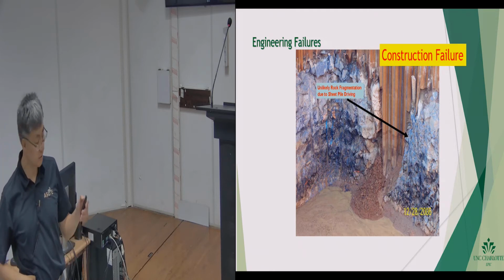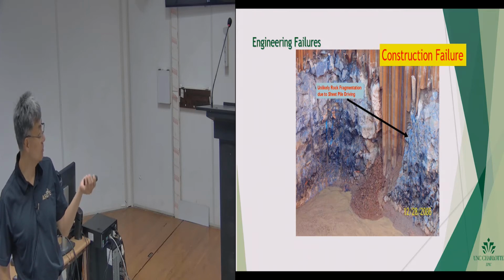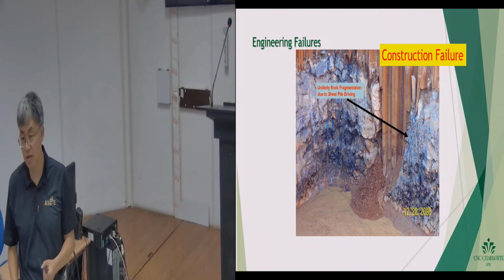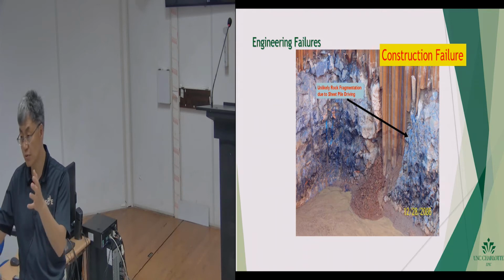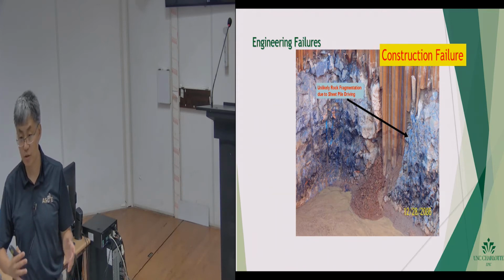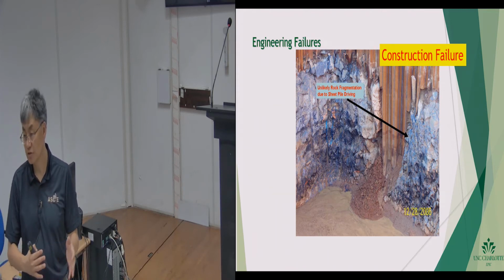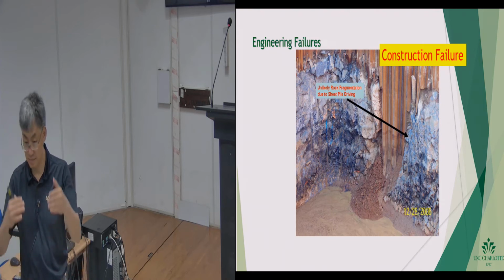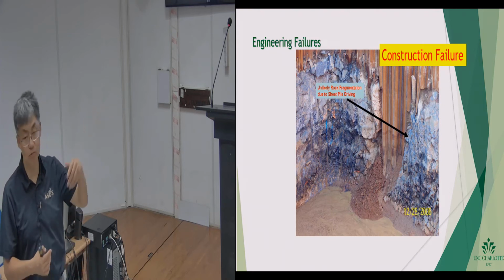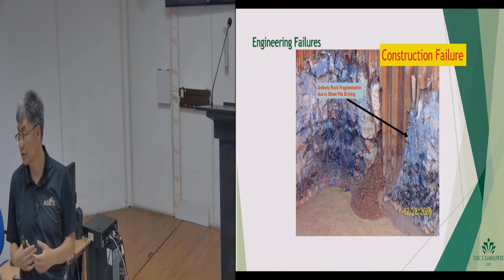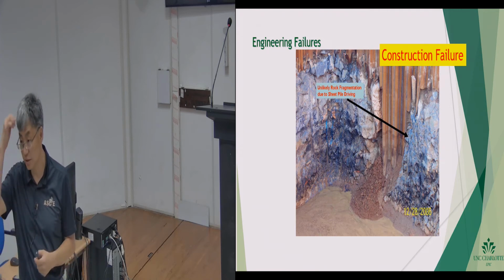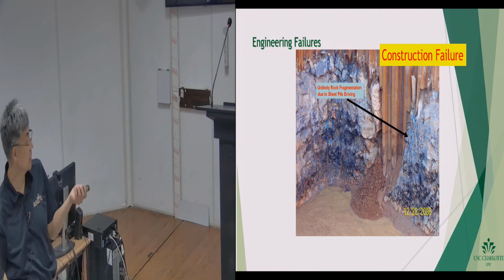The groundwater in this case happens naturally because this project is right next to a river. So we know that they have very, very soft soil, but the piles are supposed to be able to protect the area from any groundwater seeping. So these are the cases.